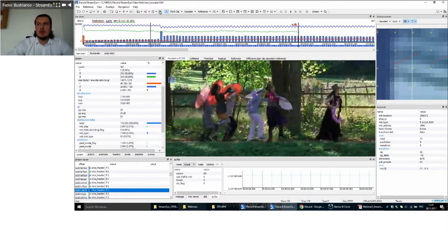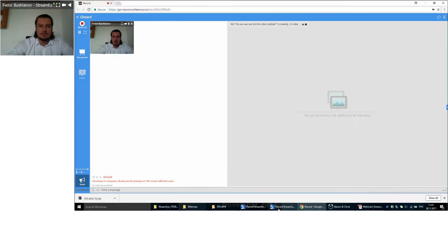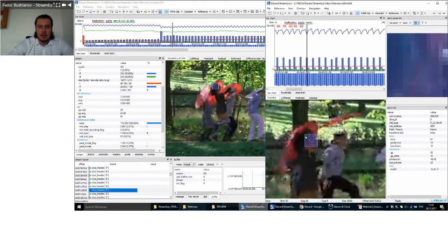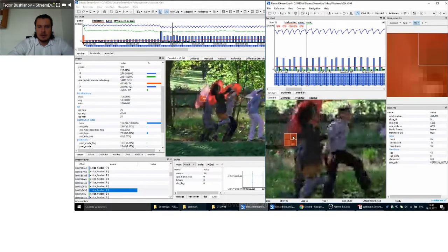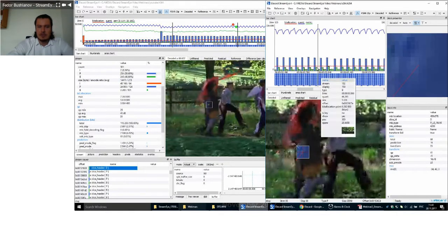That means it will start to listen for commands from another opened StreamEye instance, and it will follow all the same actions that the user performs with the other instance. So I click on listener mode, and then I move, and you see that when I'm navigating over macro blocks in one StreamEye instance, my second, originally opened StreamEye also navigates through the same macro blocks.